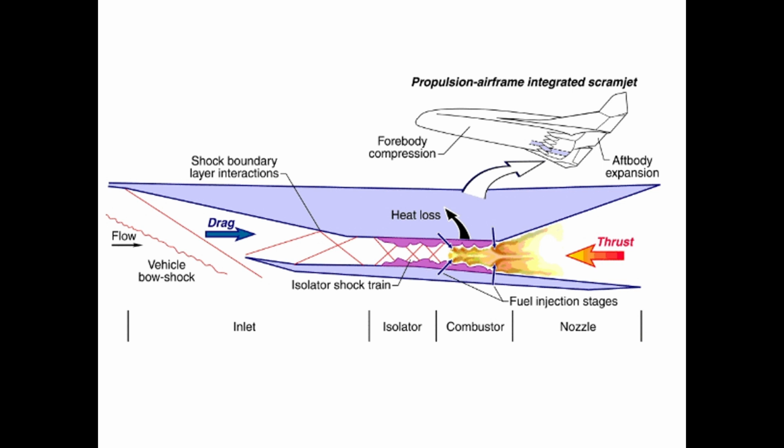pressurized, more energetic fluid, which is compressed from atmospheric pressure to more than 5 or 6 times. When the fuel is injected, it will burn and create thrust by moving through a divergent or convergent-divergent nozzle.